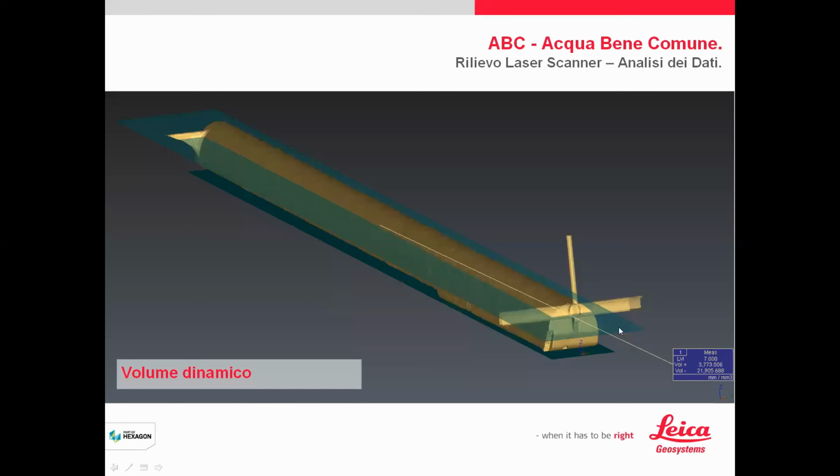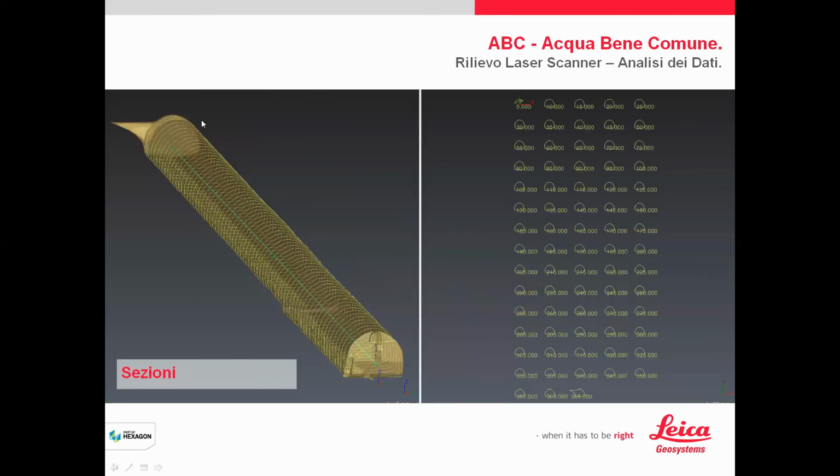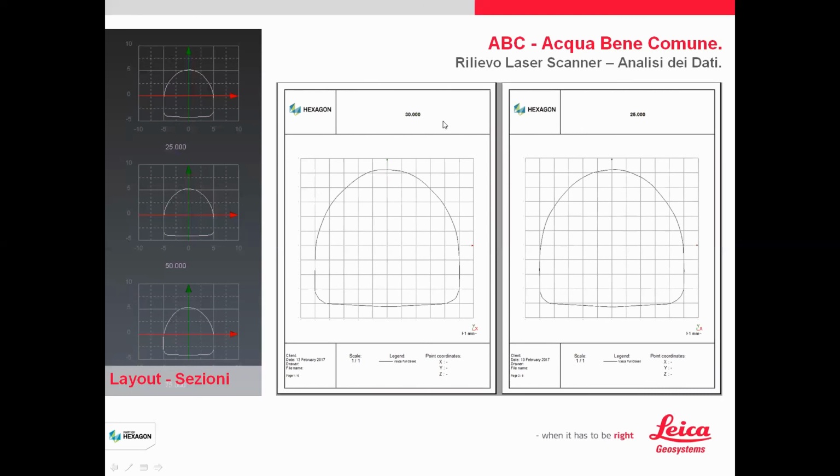After these 2 points, I created an overlap map with Google Maps, okay? Before this, of course, it's possible again to create the green path. In this case it is green, before it was red. And using this green path, it's possible to create all the cross sections in one click. And after this one click, it's possible to save in a 2D CAD or in a 2D PDF. Okay. Of course, from the mesh, it's possible to export a 3D PDF of the object.